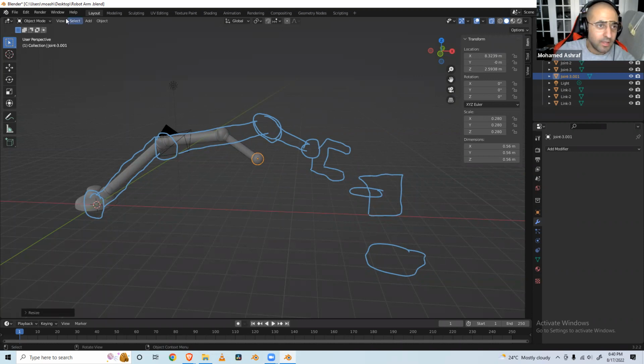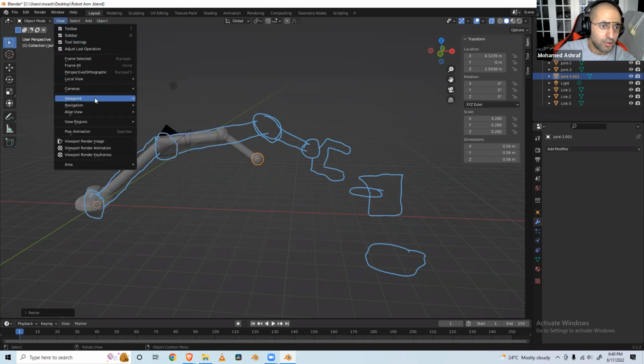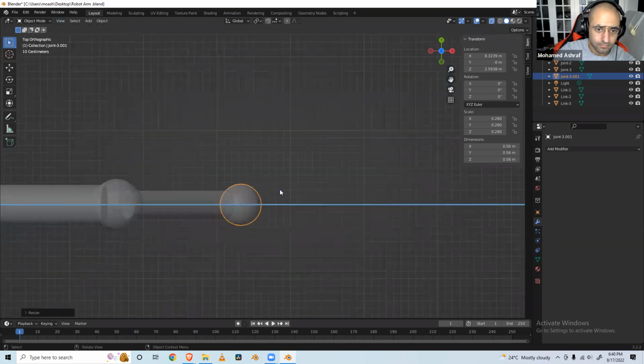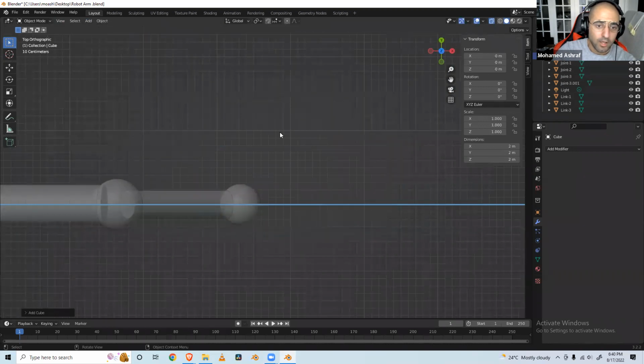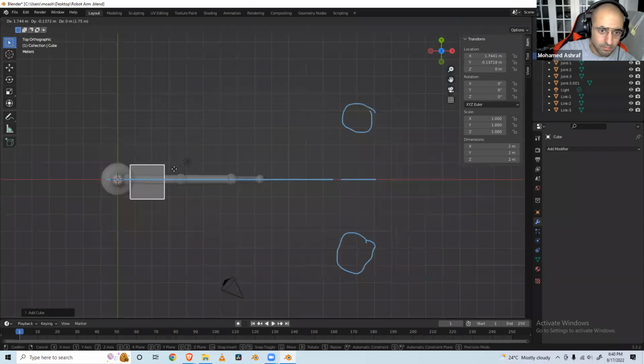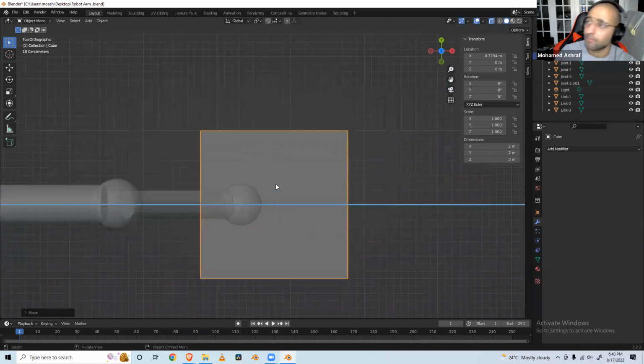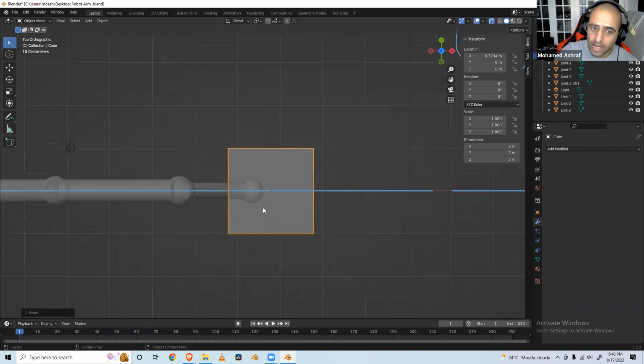So in the spirit of that, I'm going to go to top view. I am going to add a cube. I'm going to move it close to the end effector, but I want to snap to the x-axis just to make my life easier. And usually when I'm in doubt and I don't know what mesh to pick, I start with a cube or a circle and I move my way up from here. This is a very good example of making it up as you go along, but not really, because you're following a loose plan.